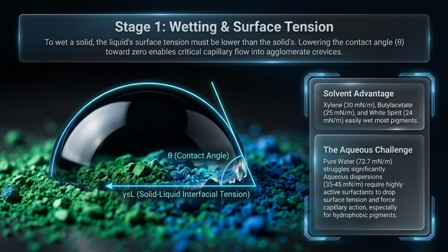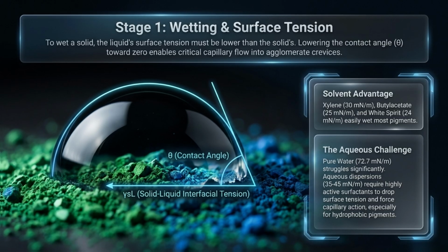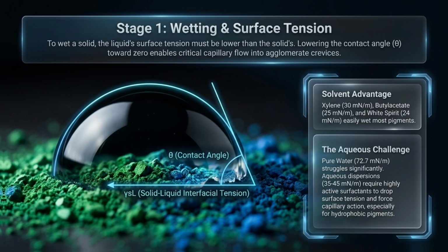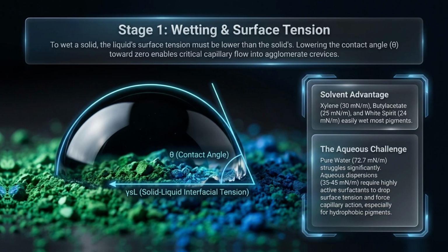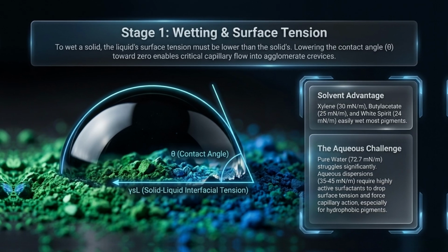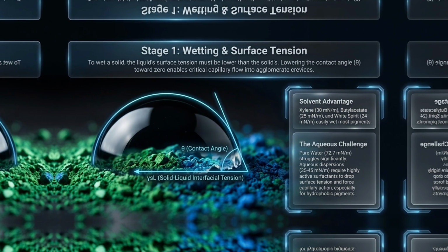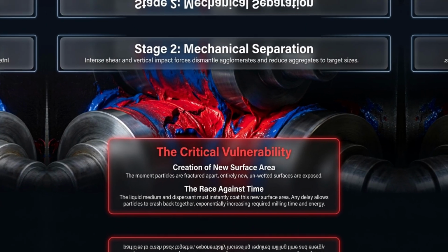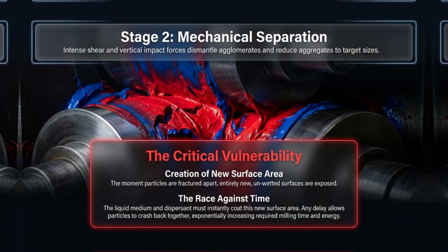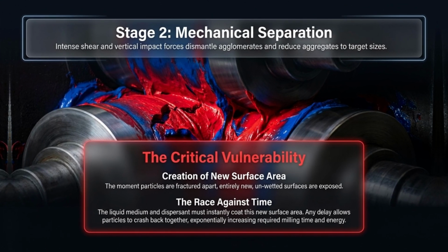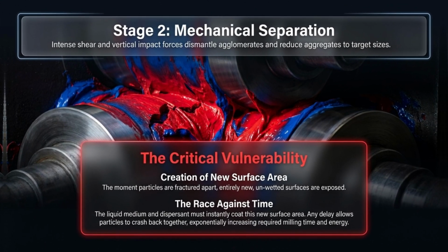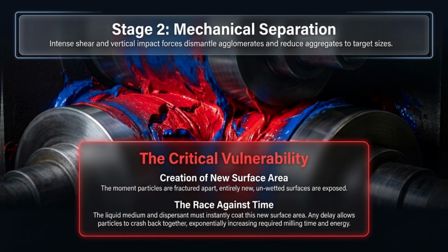However, aqueous systems present a significant challenge due to the high surface tension of pure water. They require highly active surfactants to drop surface tension and force capillary action, especially for hydrophobic pigments. Mechanical separation. During mechanical separation, intense shear and impact forces fracture particles down to target sizes.